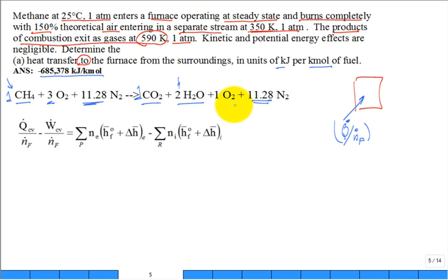Now, this may take you a couple lines to get there, but I encourage you, if you know you're going to do an energy balance, get numeric values, single entities for those stoichiometric coefficients. Go ahead, because this will probably be like 3 times 3.76. Calculate it once, put it down there, 11.28. It'll be a lot simpler for the math. A lot of times, last lecture I had, oh, that's 0.1 times blah times blah. No. Once you figure that out, let's take the next step, get single numbers for each of those stoichiometric coefficients. This is our energy equation that we derived or showed.